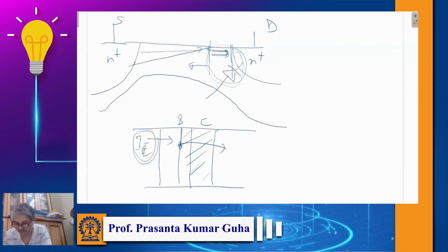So this is also true here. This is also a reverse bias region, and in the reverse bias region the current will basically increase when the channel is between drain and source. So the channel is continuous between drain and source, so then the current will gradually increase. Now once the pinch off occurs, there is no channel close to the drain.